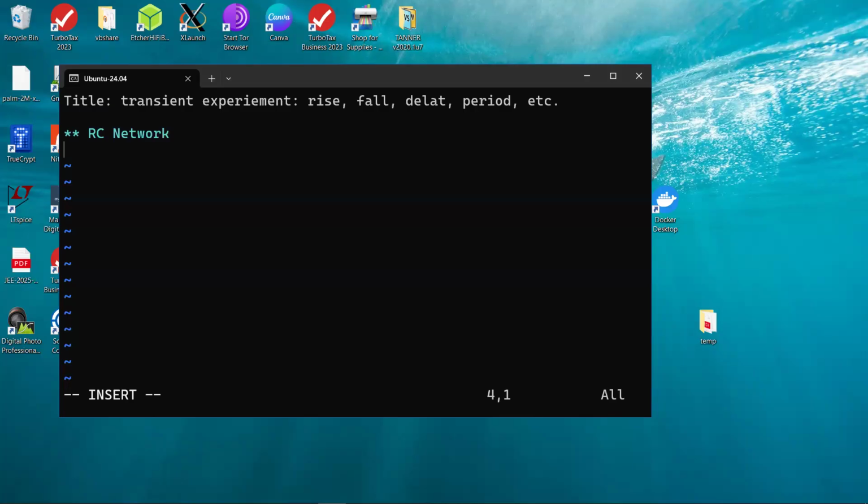So do the resistive network. You can just write R1, and for the input node you can write V in, and the output node is V out, let's say, and decide to do 1K. Then the cap is V out to, and you can write the capital word GND, which is a global for ground, and that should be 1 pico.